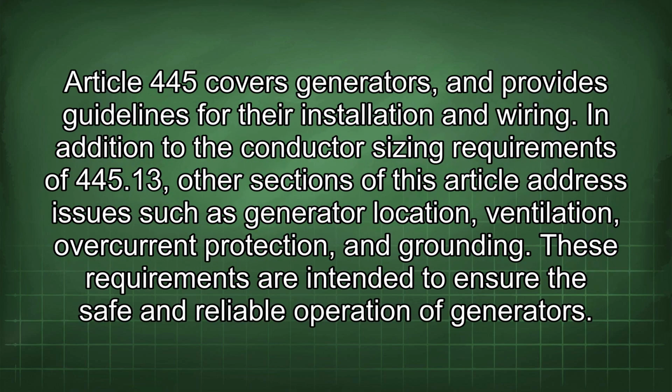Article 445 covers generators and provides guidelines for their installation and wiring. In addition to the conductor sizing requirements of 445.13, other sections of this article address issues such as generator location, ventilation, overcurrent protection, and grounding. These requirements are intended to ensure the safe and reliable operation of generators.